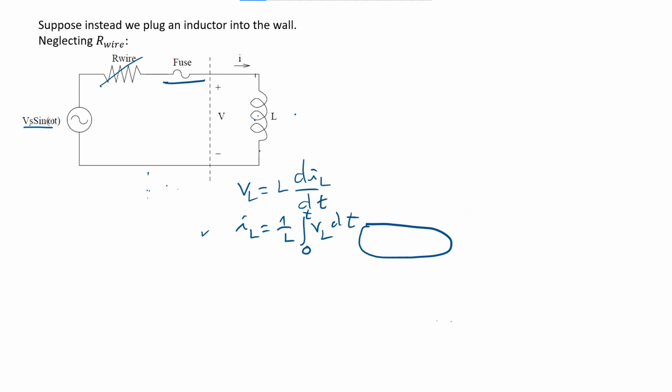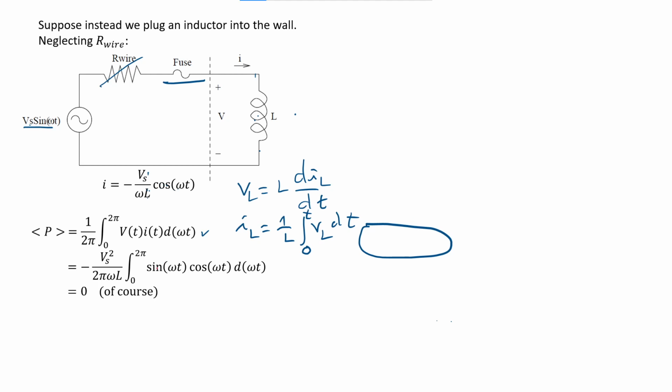Okay, next let's use an AC source with an inductor. From the differential equation we can solve that the current going through the inductor is this. Because we only have one element, we assume this to be 0, just considering the ideal case. The current can be found using the definition VL equals L dI over dt, and VL is the same as V source here.